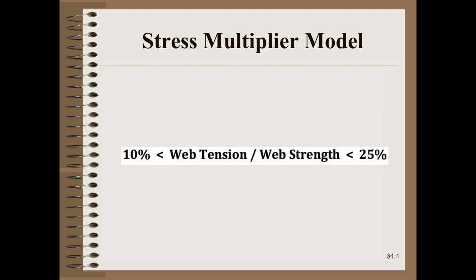In some sense, this is already implicitly done when selecting the upper end of a tension range that might be a safe setting on a web machine. The widely quoted tensioning of 10 to 25% of MD tensile strength works well for most situations, even though there are exceptions such as crepe tissue, which can be safely pulled up to nearly 50% of its yield tension.